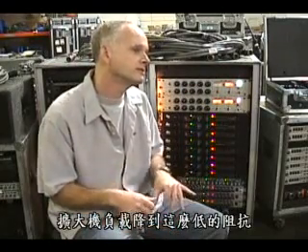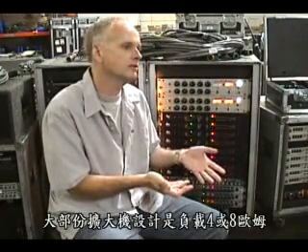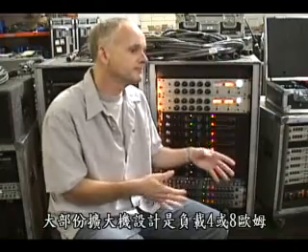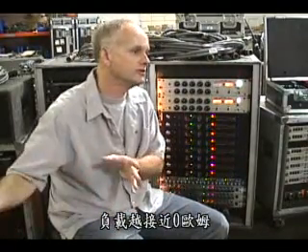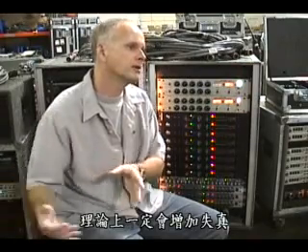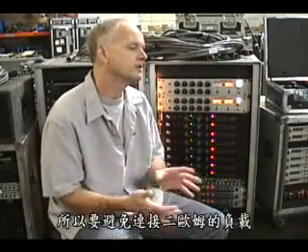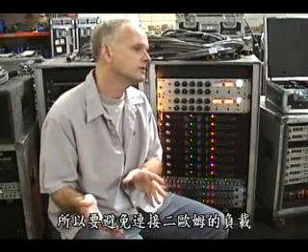The amplifier, as you drop the impedance, increases in operating temperature, and it also increases its distortion. Most amplifiers are designed to do 4 or 8 ohms. So the closer I get to this 0 point, which theoretically can't happen, the more distortion I'm going to get, and the amplifier is running quite a bit more unstably than it otherwise would. So you want to avoid 2 ohm loads. You really do.